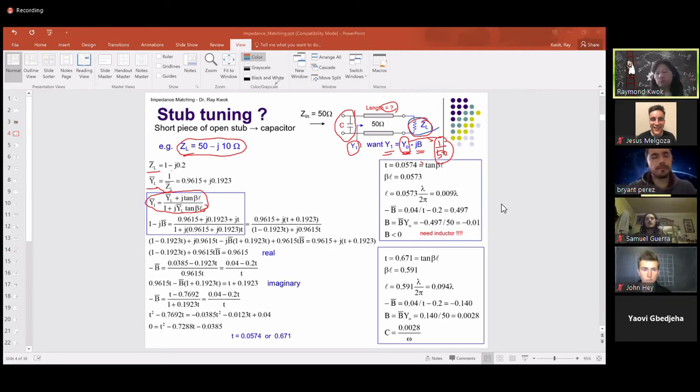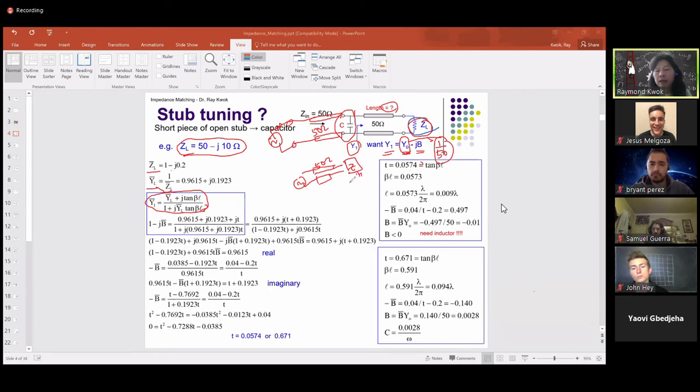Yes. But if I continue, you say, well, that means you have an unknown length of transmission line on this side before you connect to your source, right? But this is 50 ohms. If by doing that I see 50 ohms already, then my problem becomes, I have a 50 ohm transmission line here, and my source is here. But now this equivalent load is no longer the original load, it is a matched input. That's 50 ohms already.